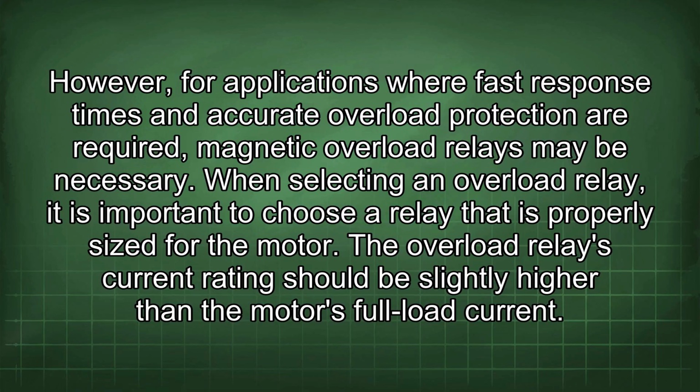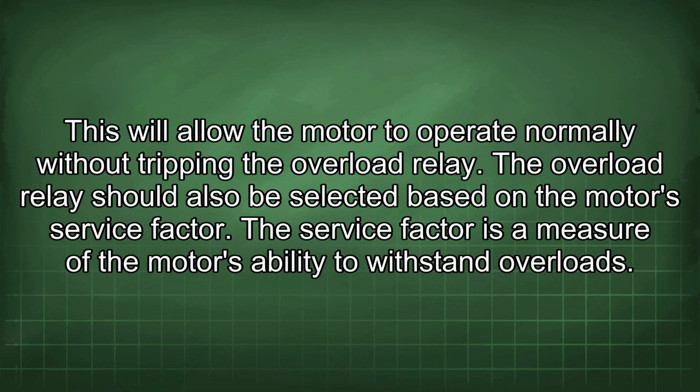When selecting an overload relay, it is important to choose a relay that is properly sized for the motor. The overload relay's current rating should be slightly higher than the motor's full load current. This will allow the motor to operate normally without tripping the overload relay.